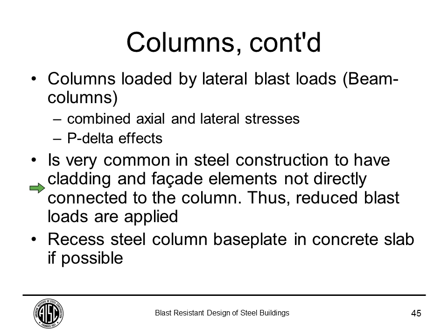This is the point that I made earlier in the presentation. It is very common in steel construction to have the cladding and facade to protect the interior of the structure. So columns are not really loaded, or at least their tributary loaded width is significantly reduced.